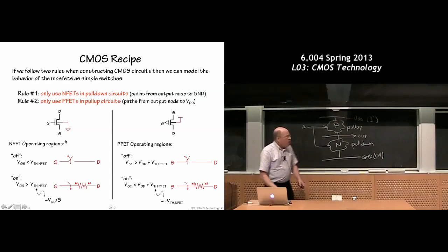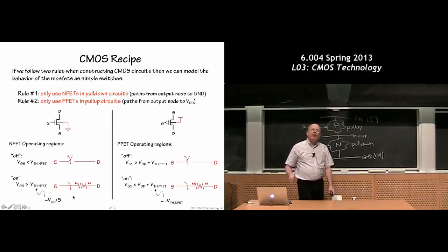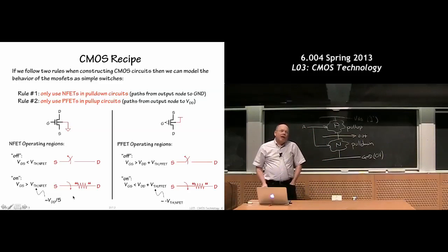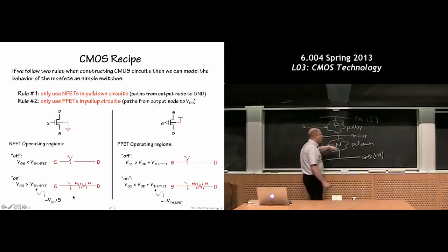Okay, so think of these voltage-controlled switches. I'm going to show you a simple model. They're either off or they're on. And if they're on, if the voltage-controlled switch is closed, then there's a certain resistance to the channel. In other words, it's not like it's a really great wire between the output. There's like a little resistor in here. And you're basically discharging or charging up the output node through this resistor, which means it takes a little bit of time to do it. In modern circuitry, on the order of tens of picoseconds to charge and discharge this node.